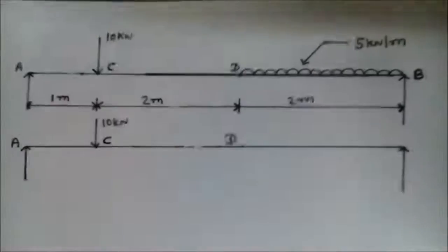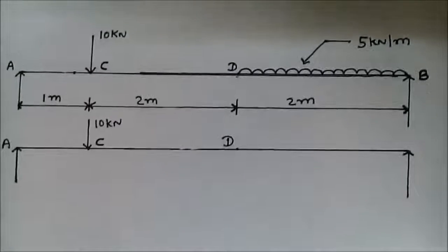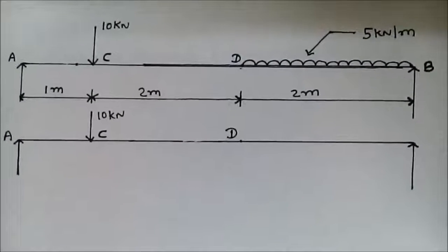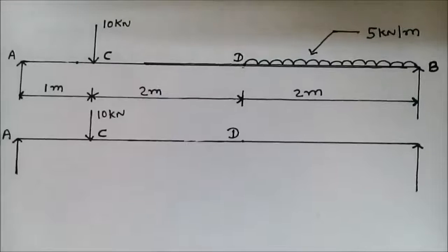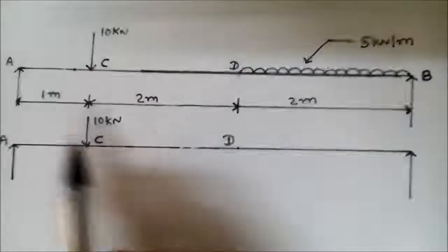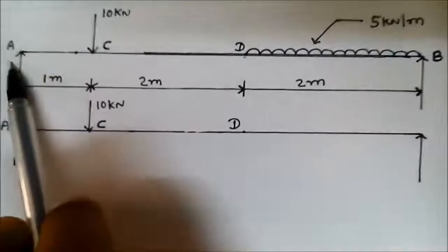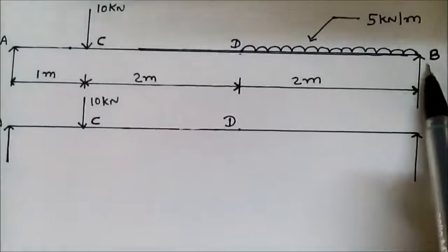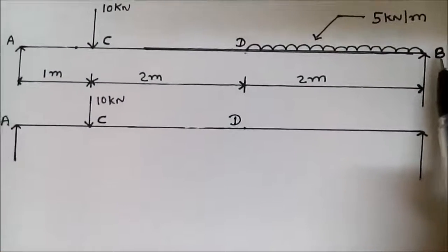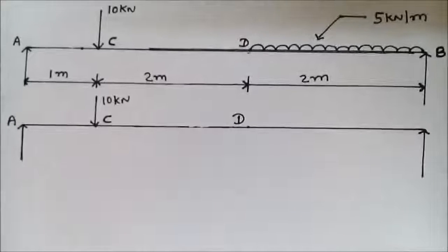Hello friends, today we discuss how to draw shear force and bending moment diagrams. As shown in the figure, there is one simply supported beam. Supports are provided at point A and at point B. The first step is to find the support reactions.